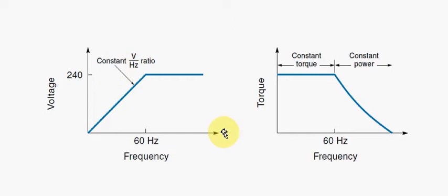So in this case, it's a star connected motor. And in the constant power region, we can increase the frequency, but we're unable to increase the voltage. If we did increase the voltage, well, then we would have a bit of smoke coming out the motor and potentially have a very expensive toaster. So boost comes into play at the lower end, around about the 5 hertz mark, because as we drop the voltage, so we drop the frequency. But there comes to a point where the voltage is so low that it has no impact on the motor, or it impacts on the motor very poorly.